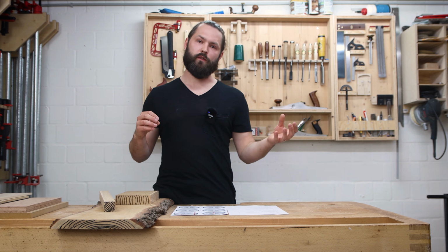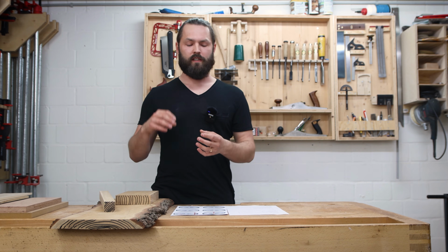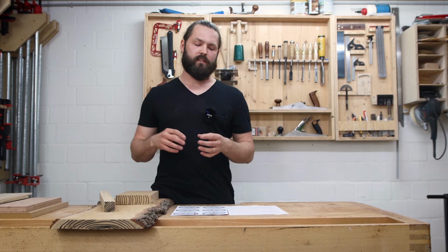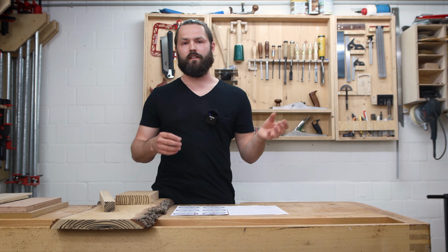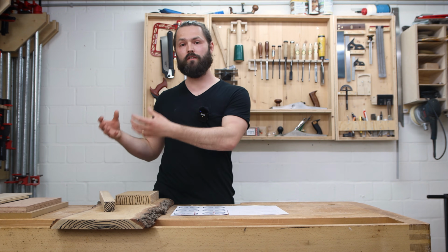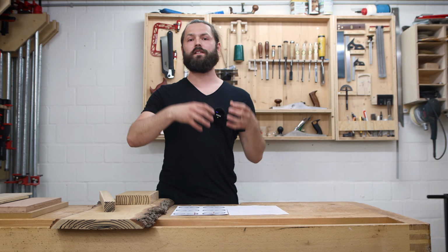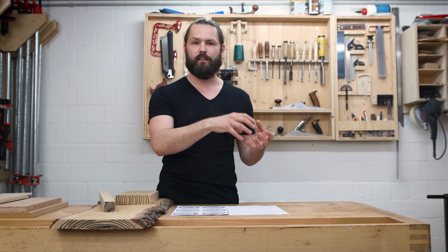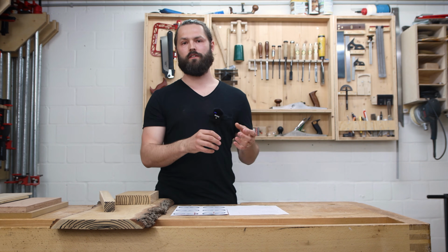This is the reason that wood is kiln dried in Europe to another moisture content level than in the US. In Europe, it's between 8 to 12%. In the US, it's about 6 to 8%. So, for example, when a bigger lumber yard from the US imports kiln-dried lumber from Germany, they will still stick it in a kiln again to dry it down to their moisture content level from about 6 to 8%.